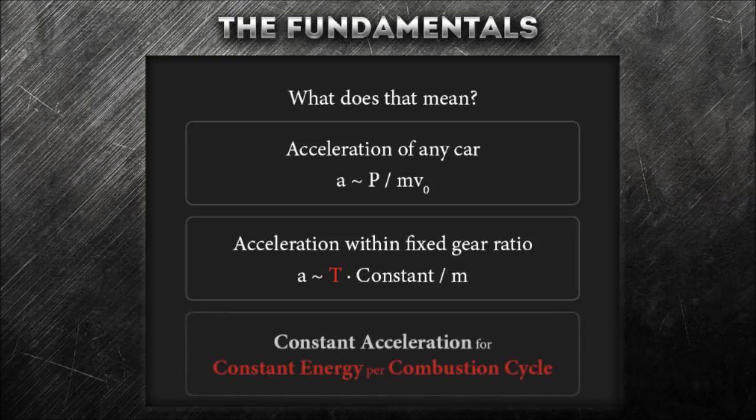Constant torque means constant acceleration. More torque implies more acceleration. It is the limiting effects of the gearbox that deceive us into thinking that torque is what accelerates a car. That is not true, as we have just seen.